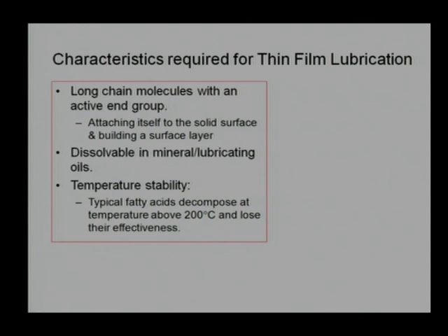Now, additional requirement is that it should get dissolved in mineral oils or lubricating oils. If there is a lubricating oil, it should get mixed with boundary additives. If it is not able to get mixed properly, what will happen? This kind of polar ends or this kind of boundary additives, they will get separated. We do not want that. We want complete dissolvement of the additives in lubricating oil.